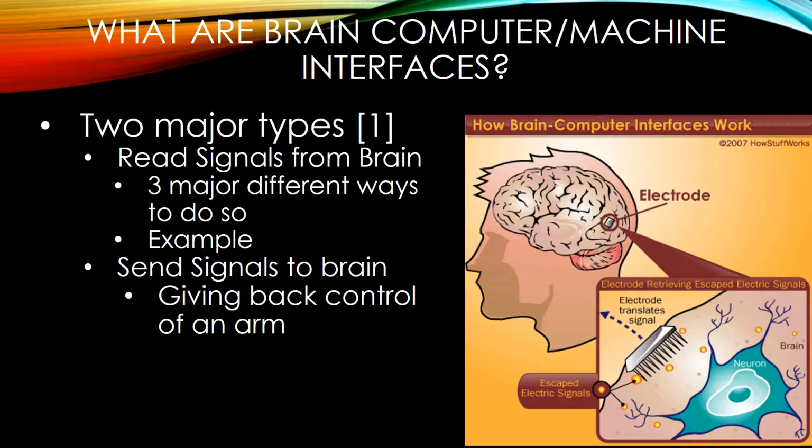The second way is using an fMRI machine or an MEG machine to measure brain signals. Both are very large and expensive and will probably not be used for small portable brain-machine interfaces. The last major technique is using near-infrared spectroscopy by shining an infrared light onto the skull. Of these three, the most popular method that's currently being used in brain-machine interfaces is using electrodes to get EEG data. The EEG data is then taken in and processed, so it could be used to power something such as a piece of machinery with just one's thoughts.